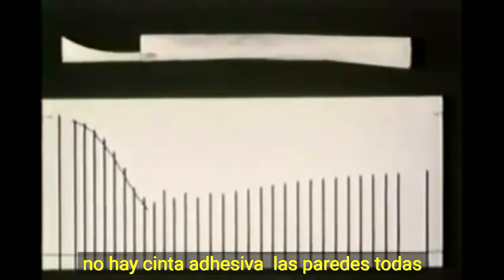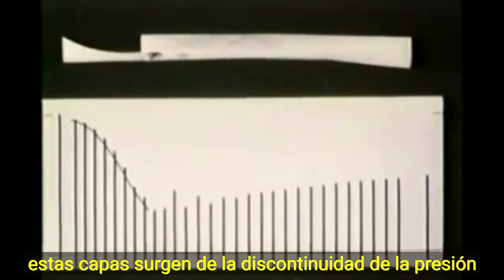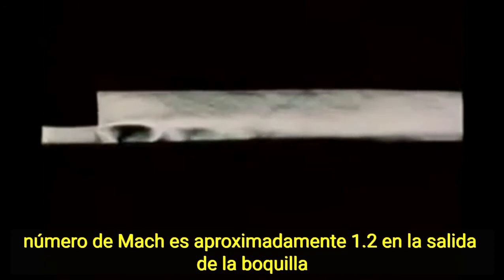For this experiment, there is no tape on the walls. All of these waves arise from the pressure discontinuity at the corner. The Mach number is about 1.2 at the nozzle exit, and the flow is adjusting itself to low back pressure through an expansion wave.